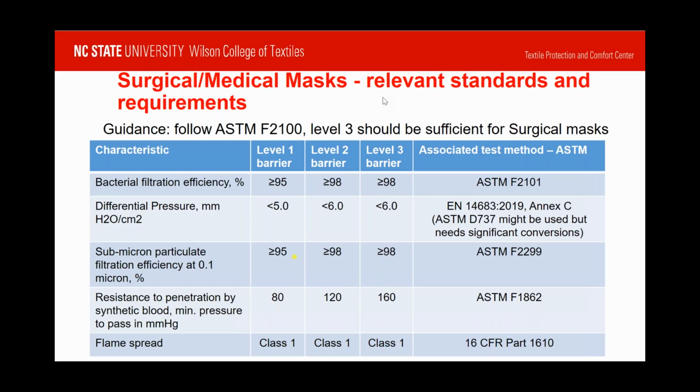The material needs to show 98% efficiency against a particulate challenge that is slightly larger than the ranges I mentioned for NIOSH. It follows ASTM F2101. Therefore, for the material, it's slightly easier to reach those levels because the particles are larger than the 0.3 micron particle size I mentioned before.